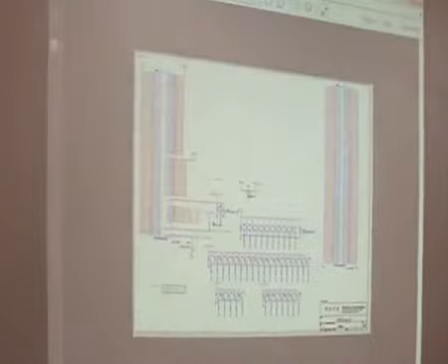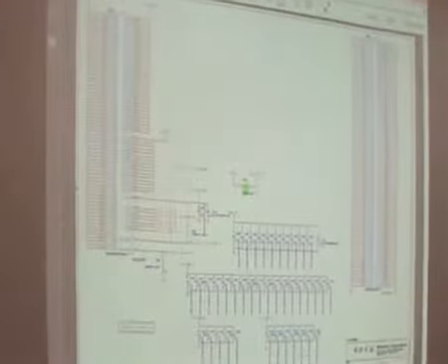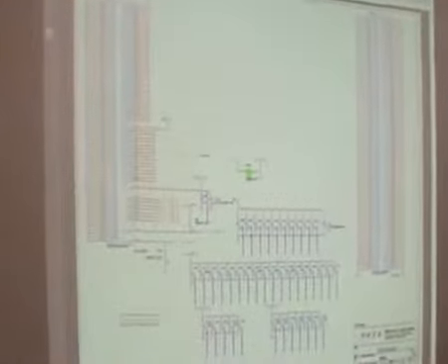Yes, here. This is the power supply of a processor. Any kind of Intel processor requires three kinds of supply. One is VCC core. A common misconception among people is that a processor requires only one supply, that is core voltage.